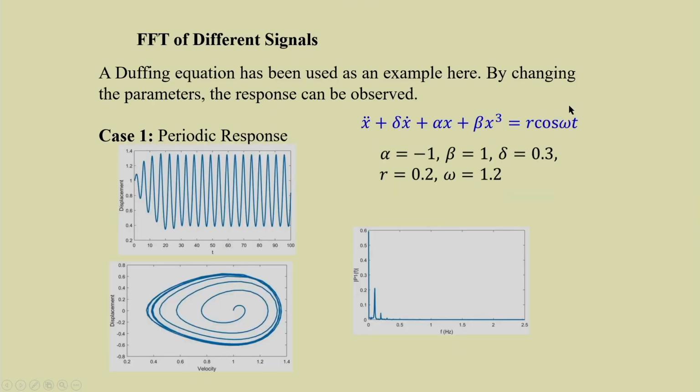So, you can plot the DFT or you can plot the FFT. In FFT you can plot the amplitude, or you can plot the power spectra. The power spectrum can be obtained by multiplying the amplitude. Actually, this FFT you are getting in complex number, so you can multiply with its complex conjugate to get the power. So, you can plot the power also.